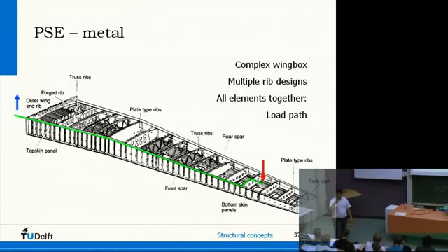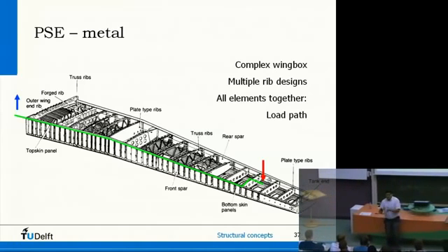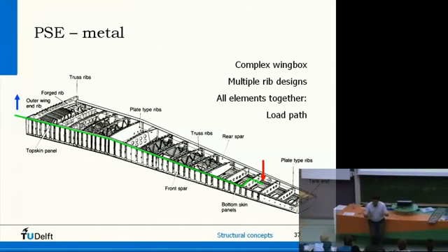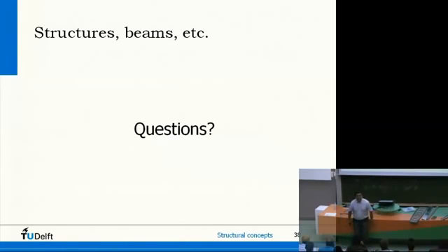So I can transport, more or less, this vertical force to the root of the wing to make equilibrium with the one coming from the side, for instance. Yeah? The same you have to do if you have a bending moment, a compression, or a tension, and so on. All these loads you have to think about in terms of load path. Okay. Questions so far?